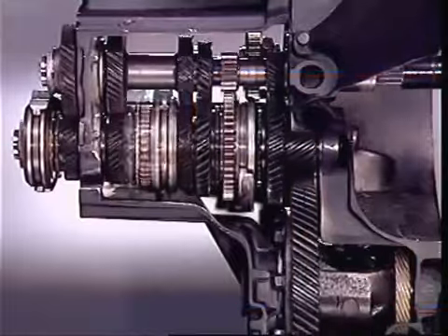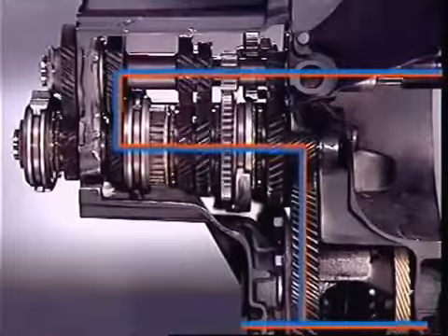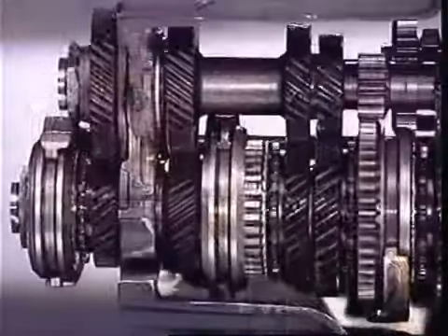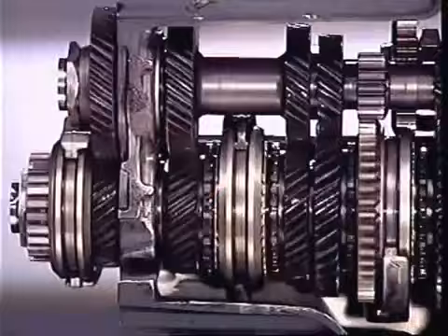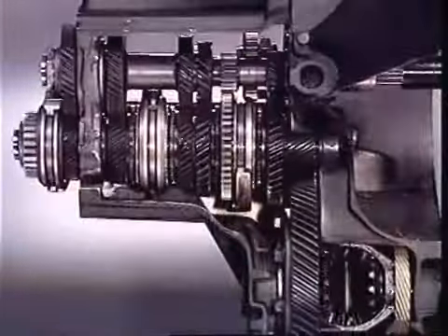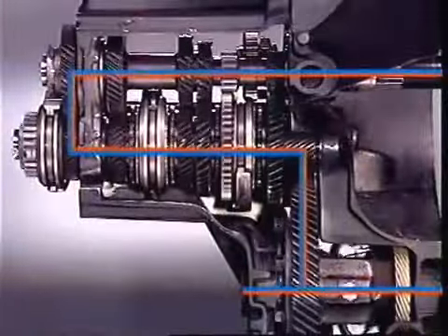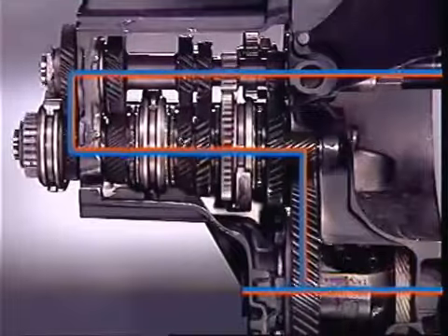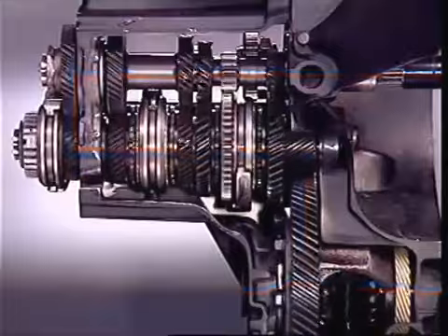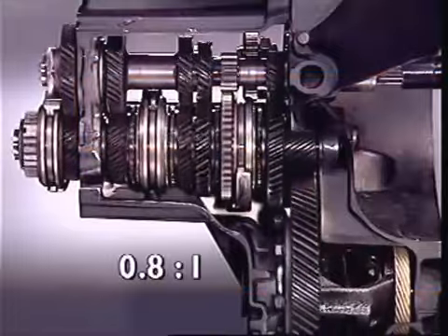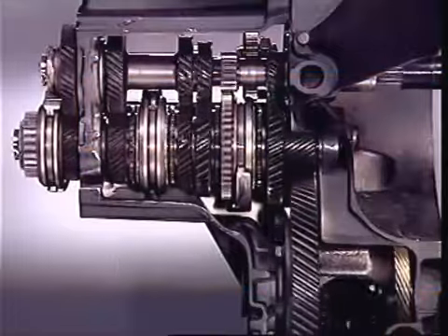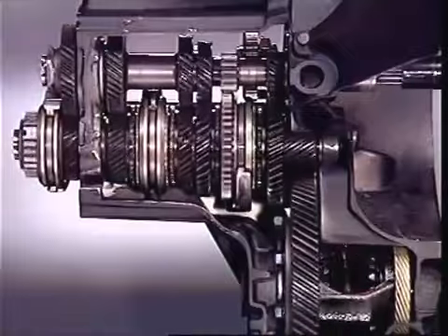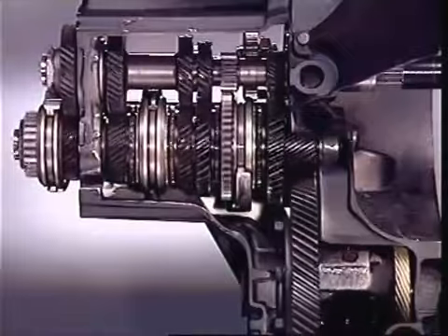The drive transfer is similar for fourth gear. The fifth gear ratio is provided by transferring the drive through the fixed fifth gear on the primary shaft to the engaged fifth gear on the secondary shaft. This is often an overdrive ratio, with the driving gear larger than the driven gear, making the driven gear rotate at a higher speed.